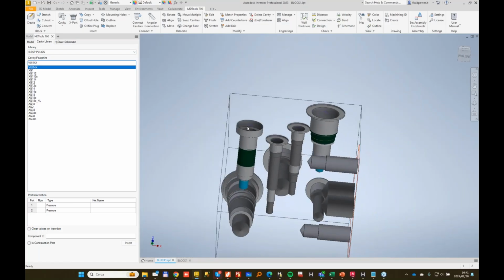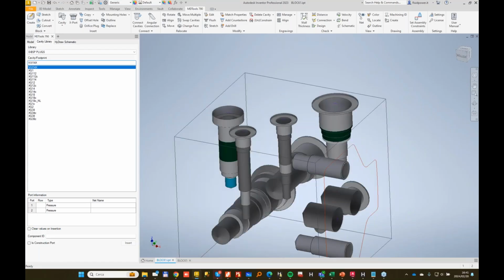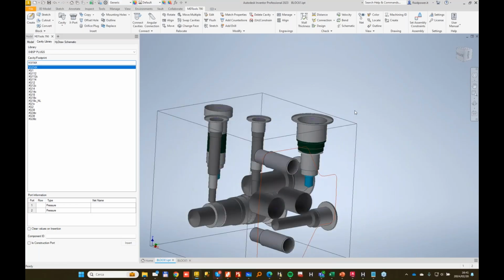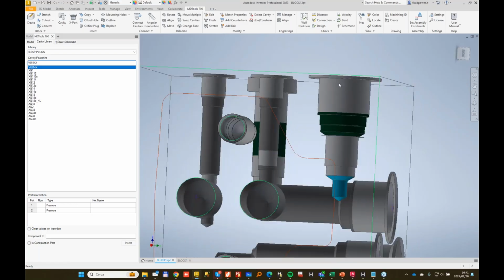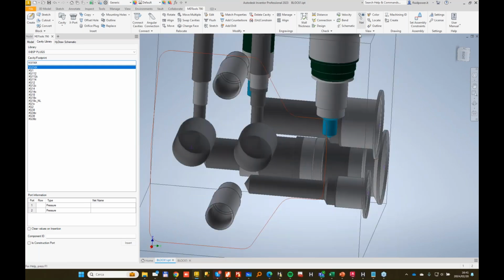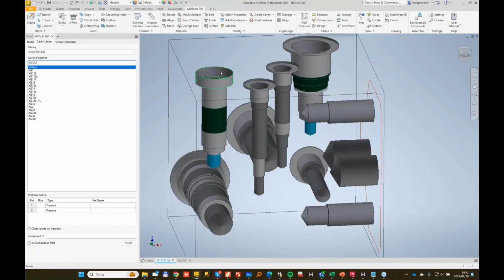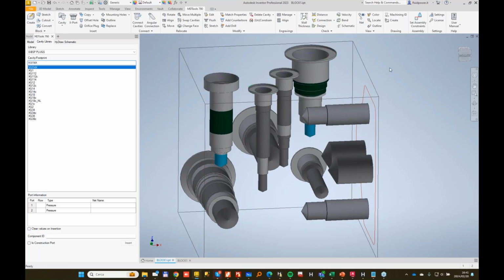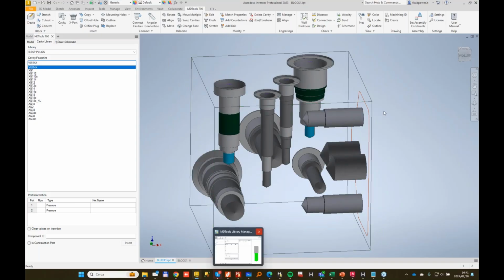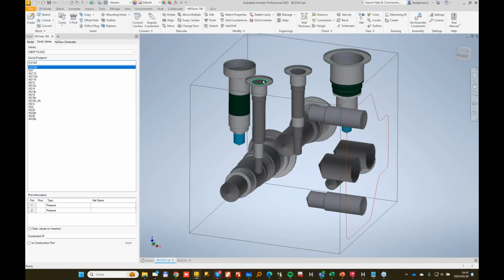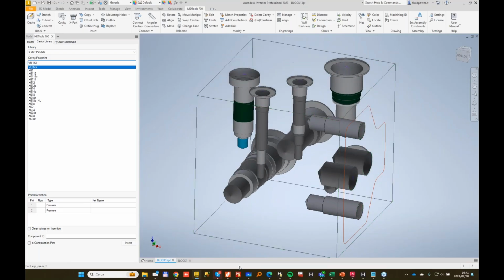So a check valve insert style, and there are similar flow regulator insert styles, may work in two fashions. One is when the cavity is placed inside a larger cavity, you can use the orifice plug, and when the cavity is placed on the same thread, you will need to model a 2-way cavity. In my standard library, since I frequently need to use orifice plugs inside a port, maybe you put an orifice plug below a test point, I have, for simplicity, created libraries like this.